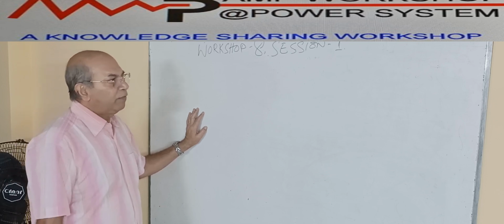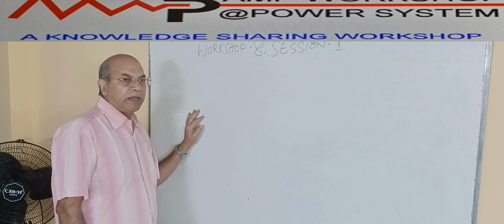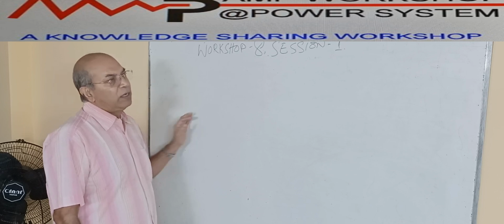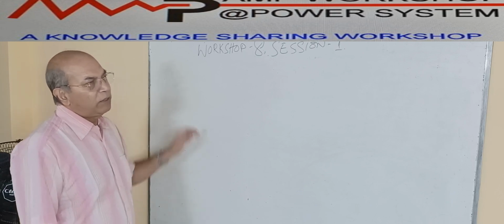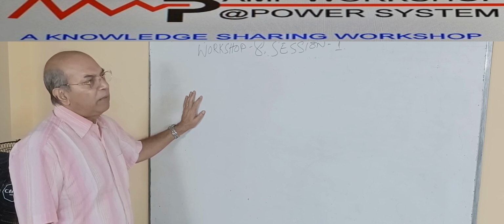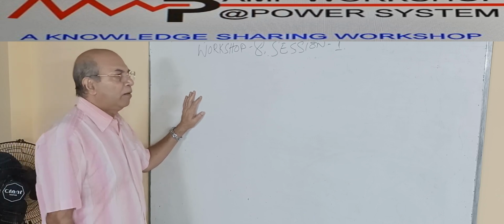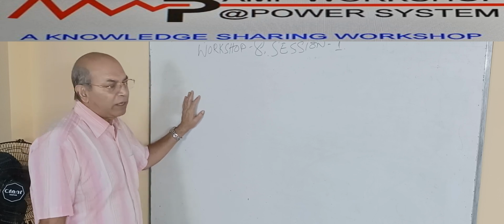In the case of indoor switchgear, it can be of two types. I have said one is a drawout type switchgear, another is a fixed type switchgear. Indoor switchgear can generally go up to 800 kV, but most installations are up to 33 kV for indoor switchgear. But above 11 kV, indoor switchgear is a fixed type. Now, why is the drawout type called drawout?